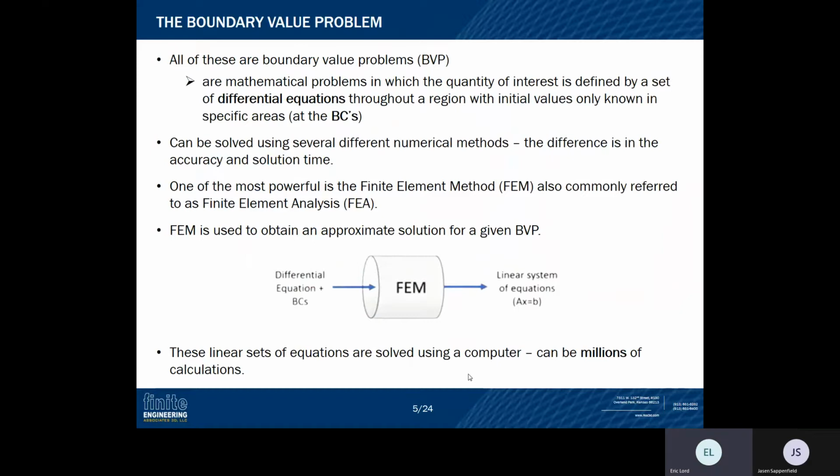And this takes us into what is known as the boundary value problem. All of the numerical methods that we'll talk about are boundary value problems. These are mathematical problems in which the quantity of interest is defined by a set of differential equations throughout a region of the problem, with some initial values only known in specific areas. For instance, we know the boundary conditions, we know where they're located, we know where the loads are located. So we have those as our initial values, and then we have differential equations that describe the rest of the region.